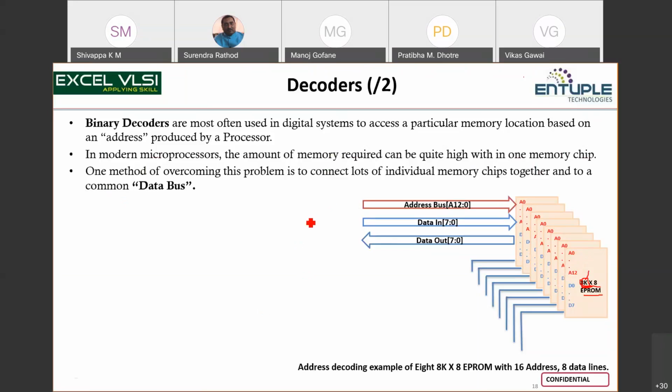So now you have this memory in binary, with 0 to 1023 locations. You said 10 address lines, that is A9 to A0. Now in order to get 2K, all that I need to do is add A10.